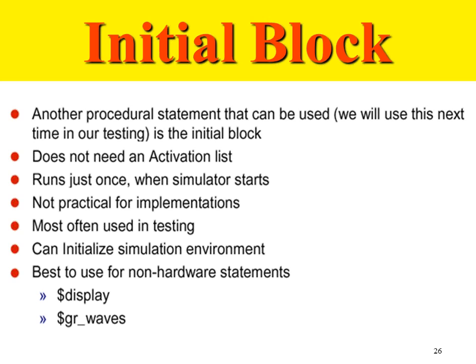No, the initial block cannot be reused by some other design. That logic is only local to that design. If you want to reuse, it can be done, but it has to be done some other way, not through the initial block. The initial block will be local to that design, so the logic declared will be restricted locally to that design.